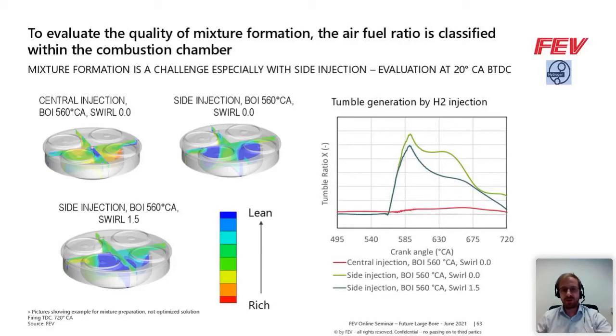And then for the side injection cases with this preliminary design, we can see we still have very lean zones also in the piston bowl, which makes the operation quite challenging, and therefore also prolongs our combustion duration, but also increases the NOx emissions.